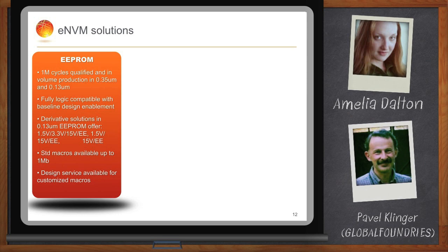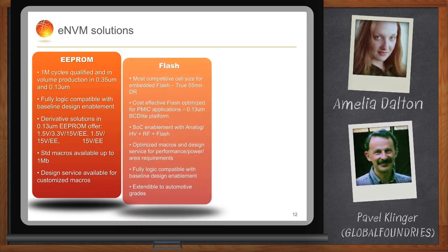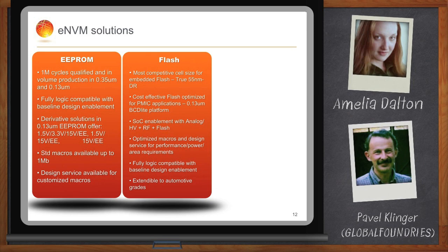Going forward, we are also enabling our NVM capability in the eFlash area, and we are going to offer eFlash, or embedded flash, capability at the 130 nanometer node, 55 nanometer node, and later on at the 40 nanometer node. So this embedded flash capability will address every customer application, including automotive microcontrollers, smart card, industrial microcontroller, and also wireless systems on chip.